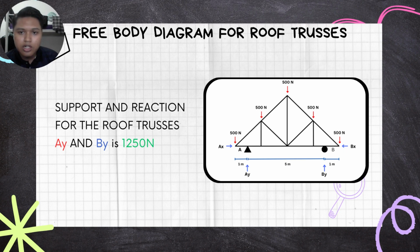This is the free body diagram of roof trusses. There are two support reactions that can be assumed, which are A is pin and B is roller. There are three reaction supports. Assuming the weight is 500 Newton at each joint, the resulting reaction supports at AY and BY are the same, which is 1250 Newton, and AX is equal to 0.